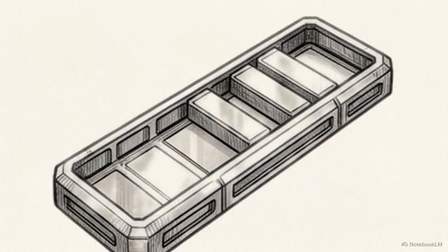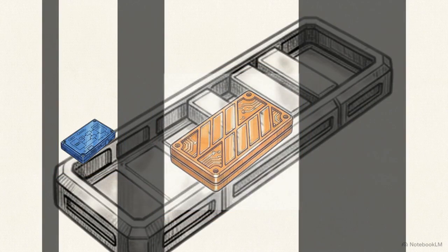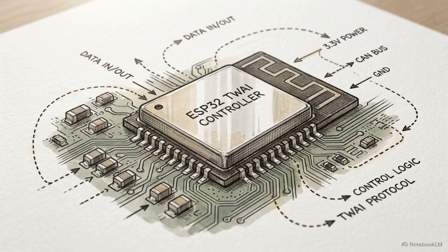These bits are packaged into a standard CAN frame with 8 specific fields. The most important parts are the 11-bit identifier dictating message priority and the 8-byte data payload holding the actual sensor values. Knowing how voltage shifts create structured frames is necessary to correctly configure our microcontroller's internal settings.